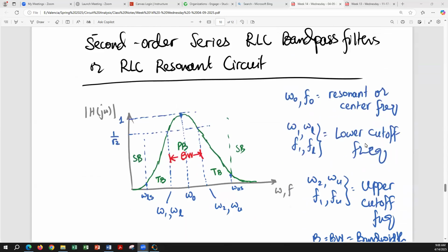We started discussing the series bandpass filter. We discussed the bandwidth: the difference between the cutoff frequency on the low side and the cutoff frequency on the high side. The difference between the two is the bandwidth of the filter. We did not really discuss it, but you have the stop frequency on the low side and upper side as well. You have three bands, of course.